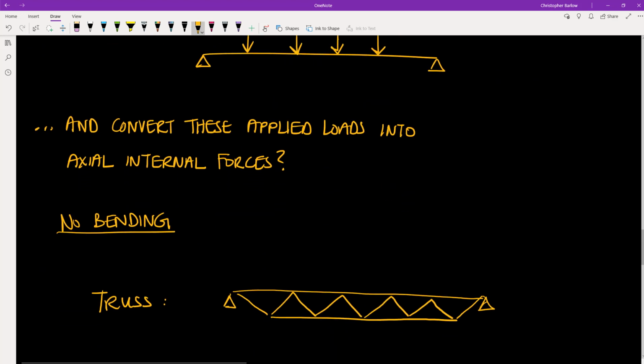Trusses and joists are horizontal members that resist perpendicular loads like beams and girders, but unlike beams and girders, they do not resist these forces through bending. Rather, they optimize the layout and orientation of the materials used to create pathways for tension and compression forces to flow through the member. So we're creating a more direct load path through the element, and we are utilizing more of the material to resist the forces. So trusses and joists are more efficient than beams and girders.